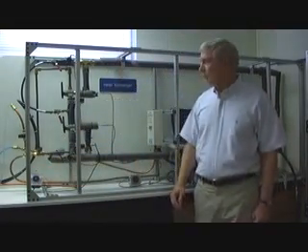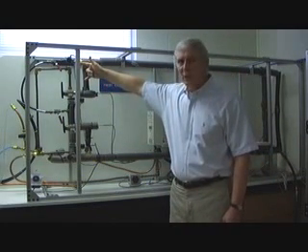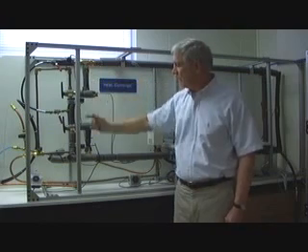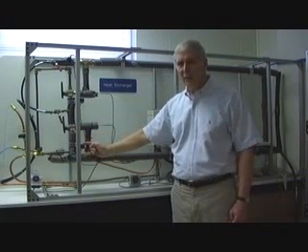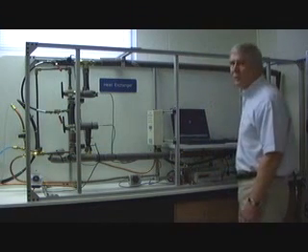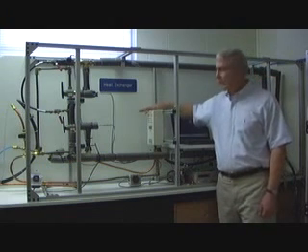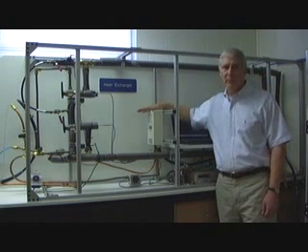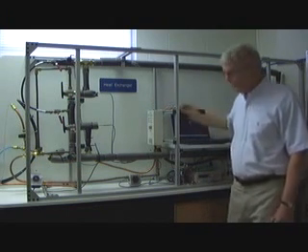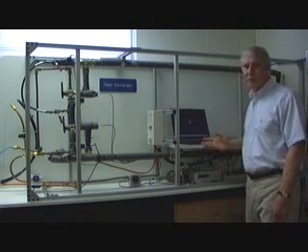Temperature is measured using thermistors. We have two thermistors at the inlet or exit, depending on the configuration. We have two more thermistors at the other inlet exit situation. And then we have two thermistors at the midpoint. There is a hot water heater to provide hot water. Measurements are made using a data acquisition board, which is located right here, connected to this computer.